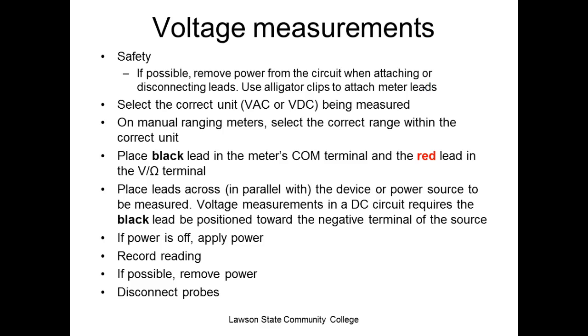So here's some pretty good safety procedures. It says, if possible, remove power from the circuit when attaching and disconnecting leads. Use alligator clips on the end of your leads if possible. Select the correct unit being measured. That's got a lot of people hurt. We have a problem in DC where people get in there and they'll measure current. And then they want to measure voltage and they forget to do what? Switch over. Yeah. And then they blow the fuse in the meter.